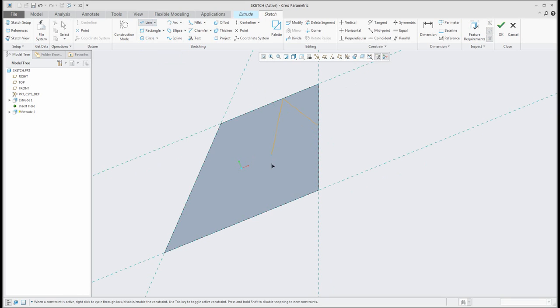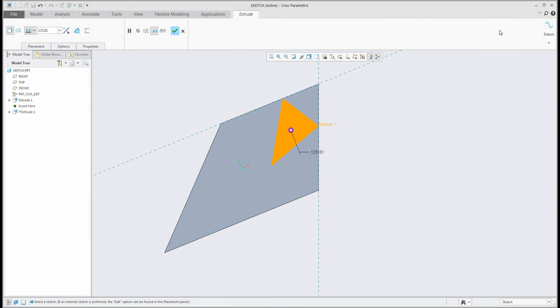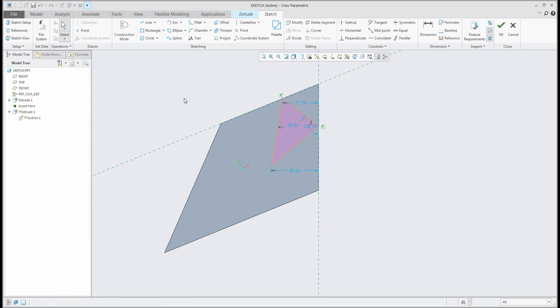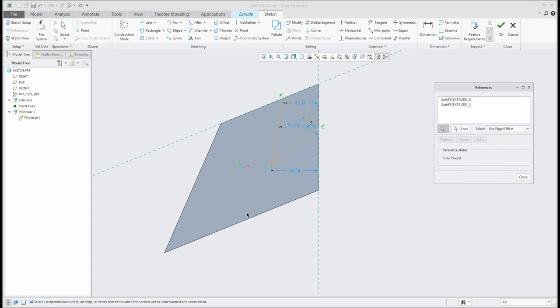For example, I will create a really easy rectangle, I will connect only two edges. You can see here that I will attach my sketch directly to two references. And the system automatically will remove unused references. So if I confirm this sketch, and then I go back to the sketch, you can see here, placement and edit, the system removed the references. So that's perfect. You can add as many references as you need, and the system will use only what you select.